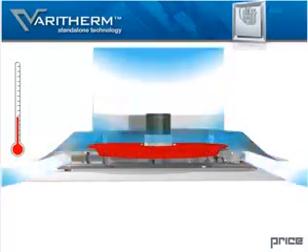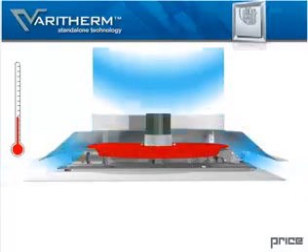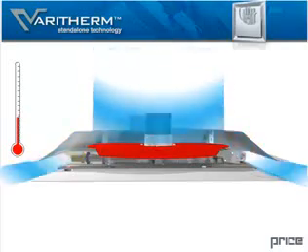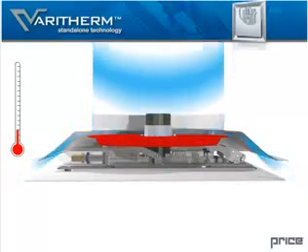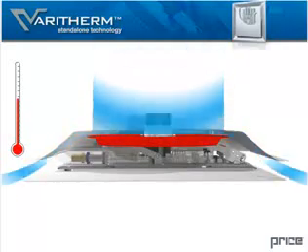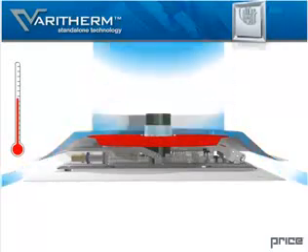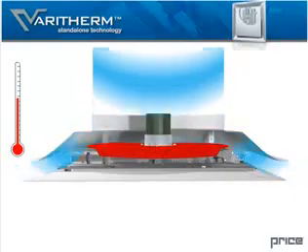In cooling mode, air induced over the thermal actuators will cause the damper to close as the temperature in the zone decreases, reducing the amount of cool air to the space. A rise in the room temperature beyond the room set point will cause a corresponding increase of cool air to the space.